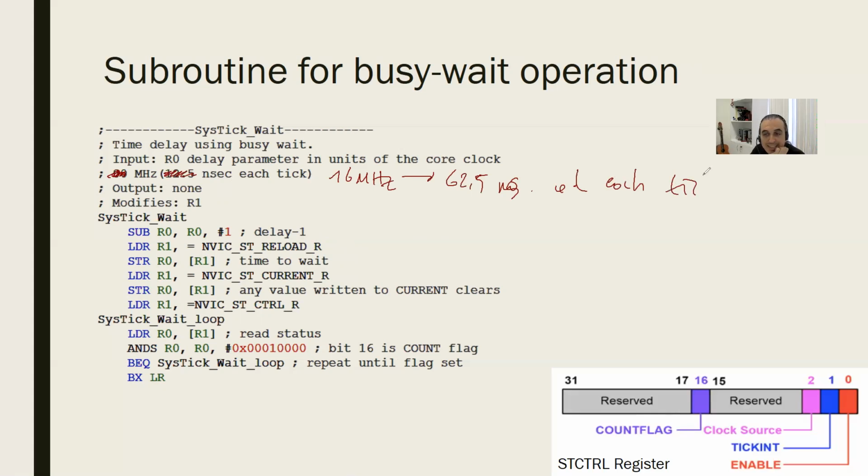We call them ticks because it's the clock signal, but the clock signals that reach the timer are called ticks. Why don't we call that clock signal again clock signal? Because clock signal is called the internal clock signal of the device. If the clock source is selected as the internal clock signal, the tick and the clock signal are the same thing. However, they are not necessarily so.